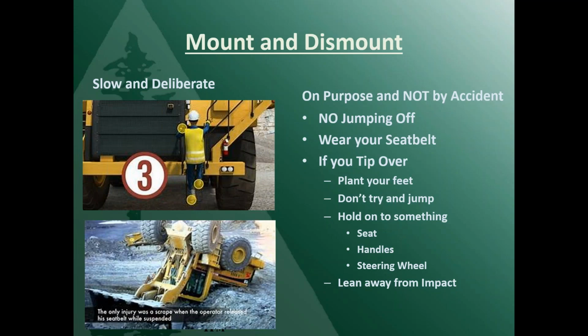Mount and dismount, we've already covered this a little bit, but this is where I see the highest number of injuries are from people jumping off the thing. Of course, you got to wear your seatbelt. And if you do tip over, we need to teach our operators to plant their feet. Do not try to jump out of it, and hold on to something, whether it's the seat, the handles or the steering wheel, and then lean away from impact.